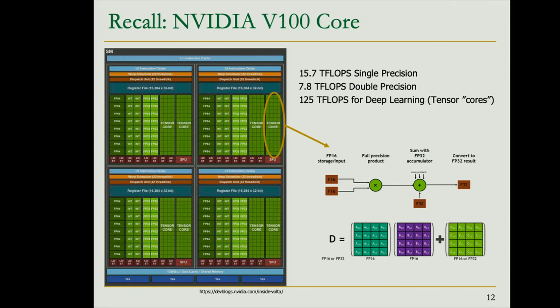And this is more or less the computation that each of these tensor cores is able to do, essentially multiplying two 4 by 4 matrices and accumulating with the original values of matrix C. So this is A, B, and C. By decomposing an entire matrix multiplication into many of these tiles and mapping these tiles onto the tensor cores, you can achieve very high throughput, which is essential these days to train networks fast and in an efficient way.